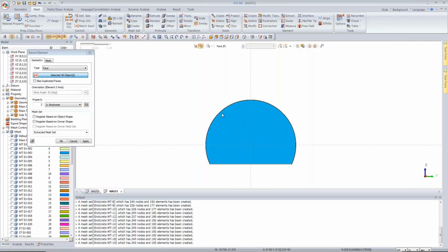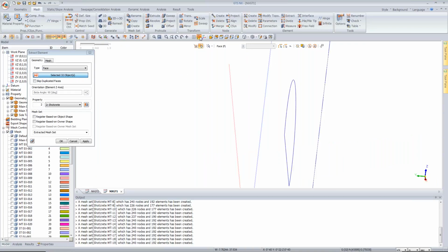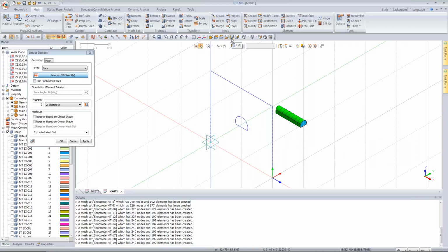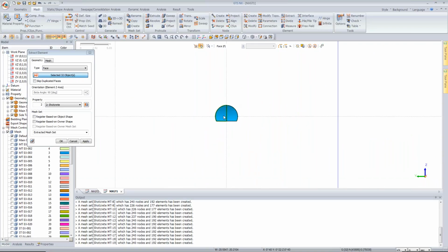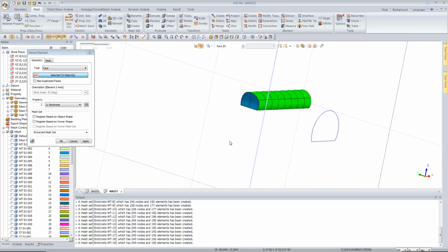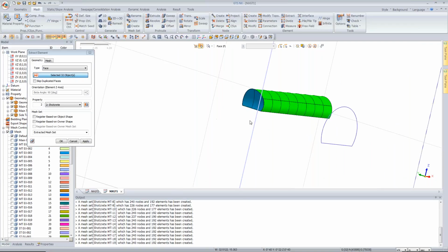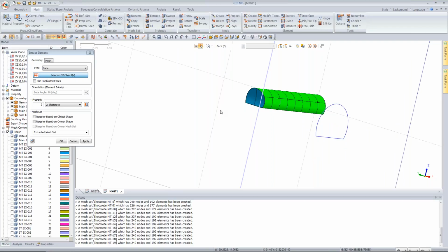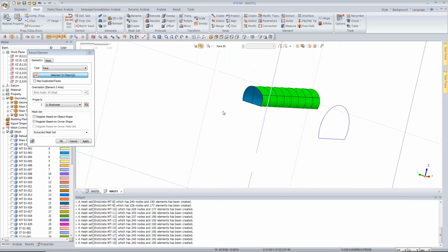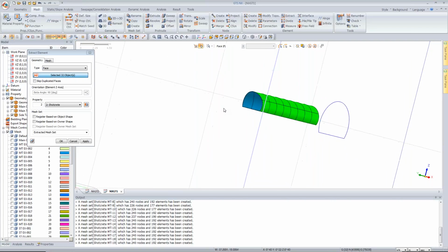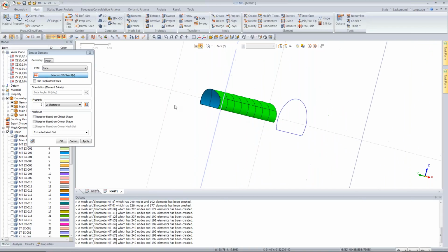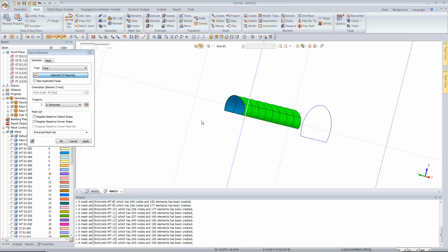Fine. I'm crossing it from both sides because many times, since this is a curve face, sorry, if I go to this view, this is a curve face, it sometimes remains unselected. So you can rotate the model. To rotate the model, everything is here: rotate, pan, zoom in, zoom out. But you can always use the mouse to zoom in and zoom out, and if you press the scroll of your mouse, you can rotate the model with the speed, and if you press control on the keyboard and press the scroll, you can move it laterally like a pan. Okay, so all the commands can be done using the mouse as well.